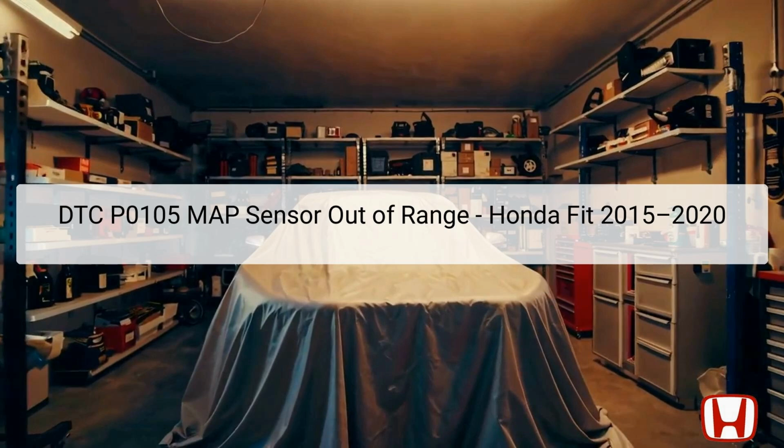In this instance, the sensor's readings are reported to be out of the normal range, indicating a possible fault. This issue can arise due to the MAP sensor itself, wiring issues, or even the Engine Control Module, ECM. Upon detecting DTC P0105, it is essential to follow a structured troubleshooting process to confirm the fault and identify the underlying issue, ensuring that corrective measures can be implemented to restore proper engine function.